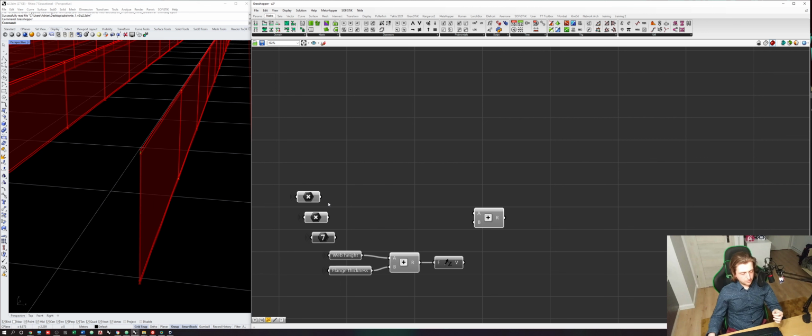Just simply add a vector to the point, because summing vectors is like summing scalars. So you don't have to use the Move component to move a point. You can use Move to move lines, surfaces, and so on. But if you are operating with principal elements like points, then you can just add them. Of course, you can also add vectors to vectors, because vectors are something like points in the definition on paper.